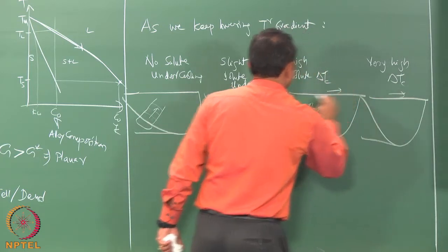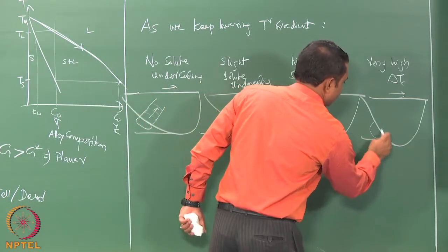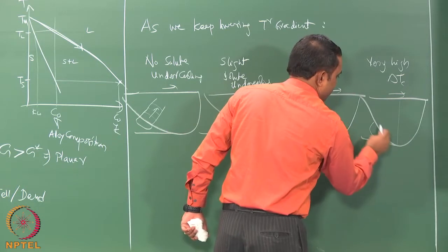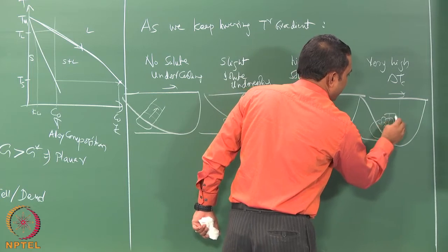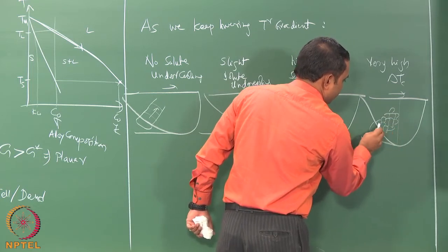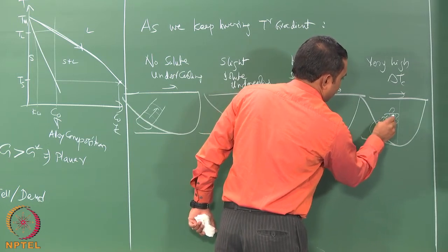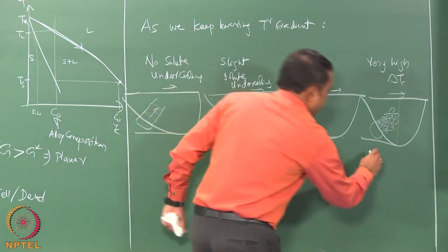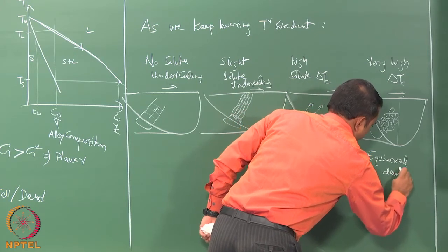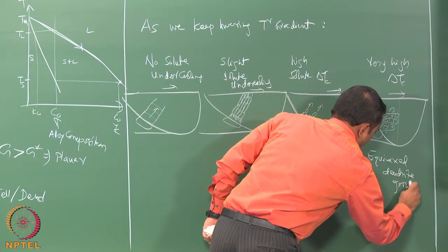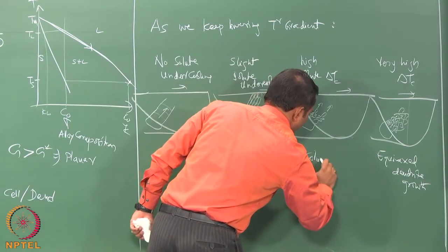in all these situations we are looking at the longitudinal section, and what you would see is that as the undercooling increases, you no longer have long dendrites that are growing. Each of these will have a lot of dendritic appearance. So, you see that there will be what is called equiaxed dendrite growth appearance. These will be long dendrites or columnar dendrites.